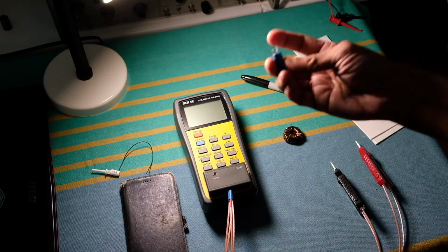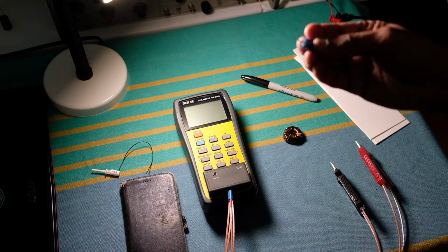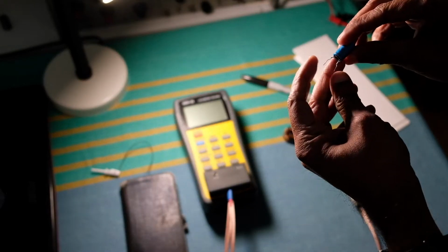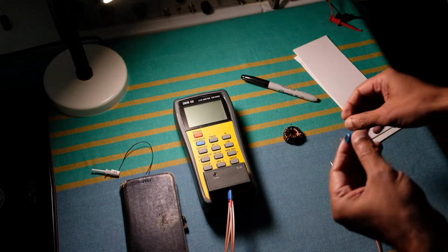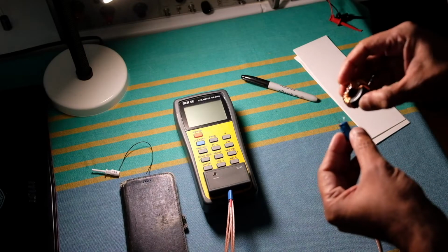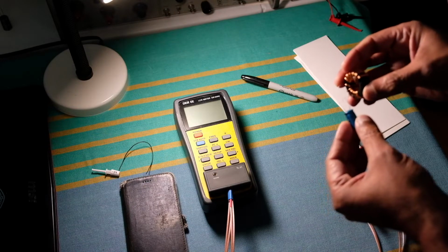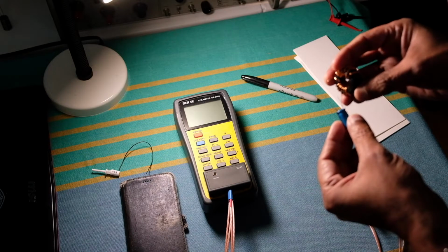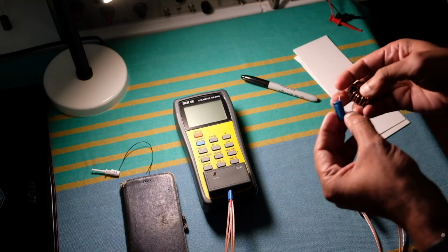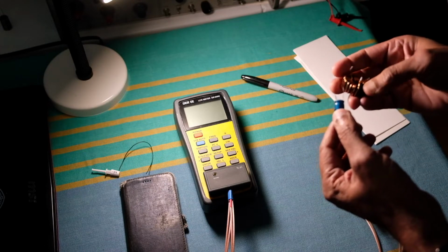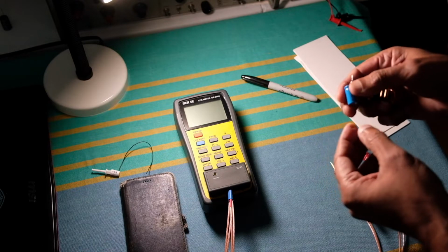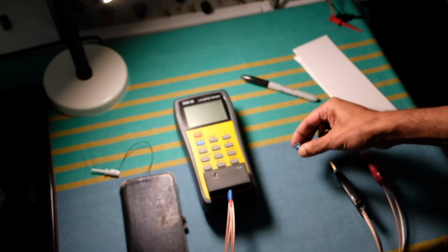So here I have a 470 microfarad electrolytic capacitor. It's got very short leads, so the effect of inductance on this one is going to be very, very minor. So in order to simulate the effect of inductance, I'm going to add this inductor in series when I do the measurement, to see the effect of what we talked about: the decrease in total reactance, the increase in capacitance because of this inductor, and also making it lossier in terms of the dissipation factor and reduction of the quality factor.